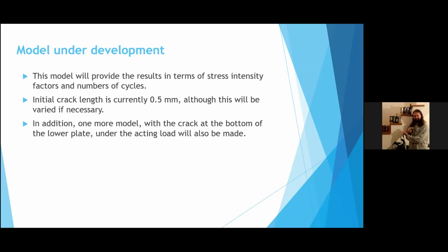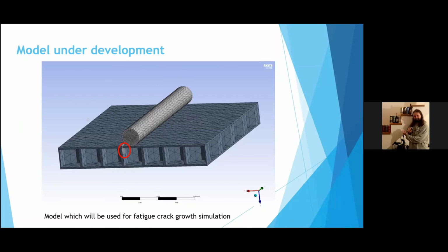So currently the initial crack length in the model is 0.5 millimeters, but that can be varied at any point. And of course, another model will be made with the crack at the center of the bottom plate below where the load is acting. So that's all I can tell you for now. I hope I'll have more time to deal with this in the future, and that I will be able to maybe get some new results in the next few days.